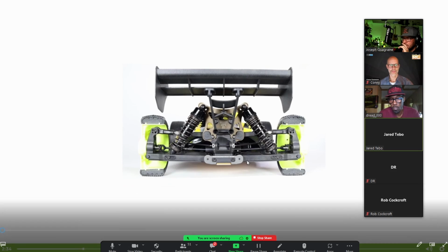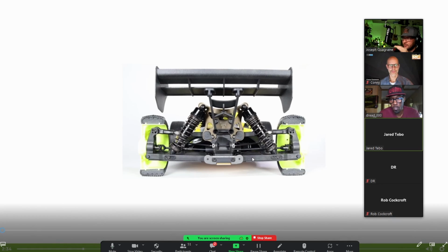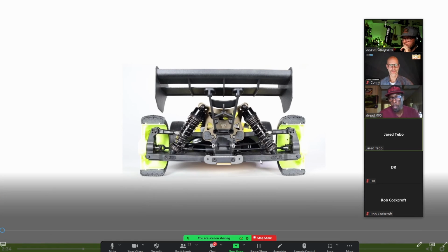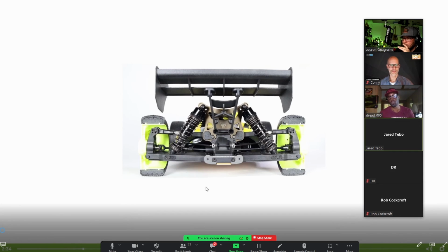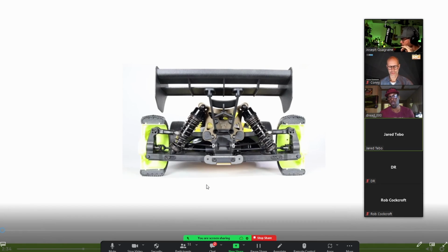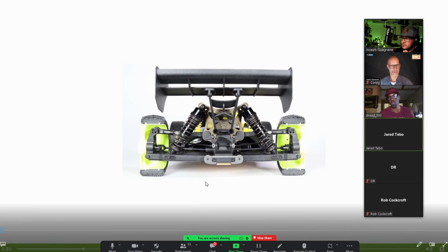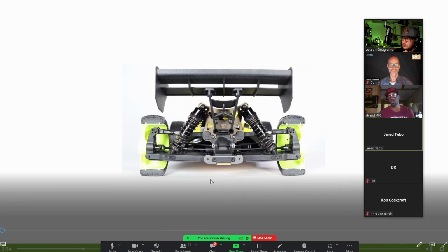I would agree there, moving those arms kind of sets the general grip of the car. But wouldn't it use? Go ahead, finish what you were saying. I was just going to say, lowering that down is less pressure being put onto the tires. If I'm at a loose track and I lower my arm down, I feel like it's forcing my tires into the track less, and the car is generating less traction. If I raise my arm up, it feels like it's forcing the tires into the dirt more and generating more traction. So on a loose condition, I like my arms raised up.